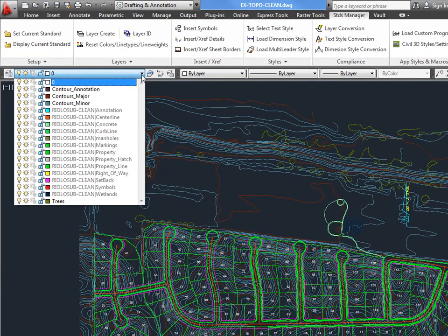A common scenario in many companies is a struggle to adhere to CAD standards, particularly once a standard has been adopted. Moving your existing drawings to that standard or taking client drawings to that standard can be tedious. In the following example, I will describe how to convert the layers of a drawing and an attached X-reference simultaneously. In this example, I will assume that the National CAD Standard, or NCS, layering guidelines will be used, and notice that the current layers are not of that form.